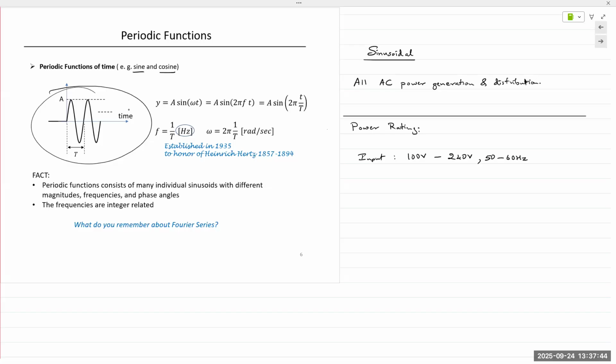That being said, if you are traveling abroad anytime, you always want to check the power rating of your device. And output, of course, could be, let's just say it's 5 volts. So it's 5 volts DC and will state 1 or 2 amps capability. So this would be a 5 times 2, 10 watt DC charger. 10 watts is nothing nowadays, right?